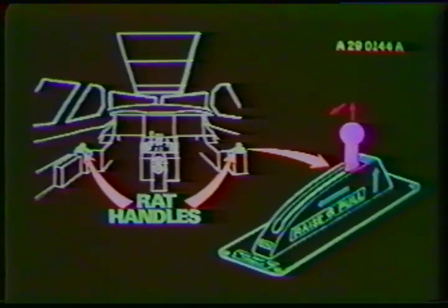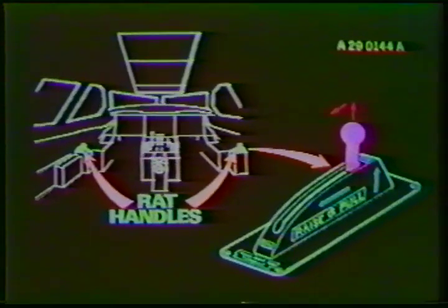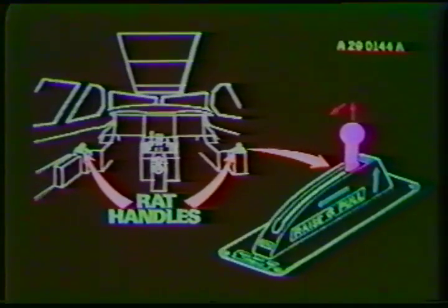The ram air turbine is extended by a spring-loaded device. Either of two control handles, one each on the captain's and first officer's side consoles, provides the means for extending the RAT. Once it is extended, retraction can only be accomplished on the ground.